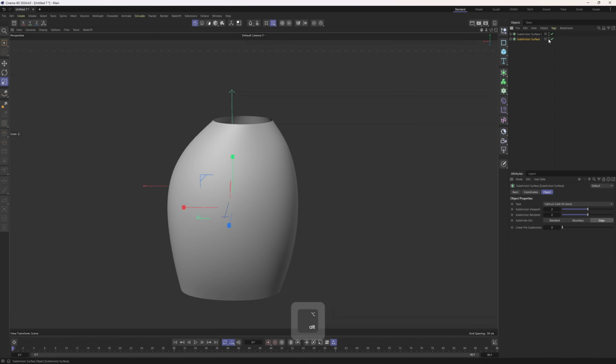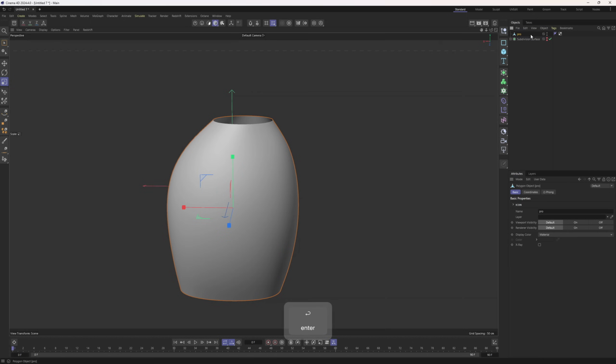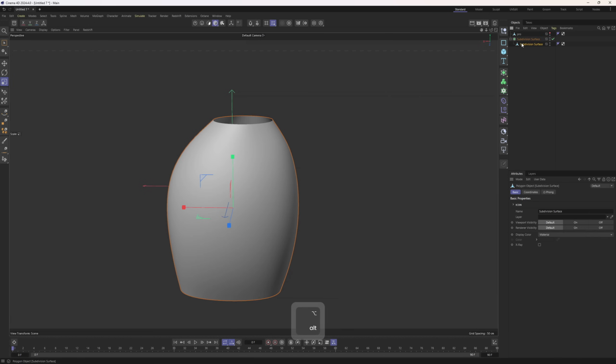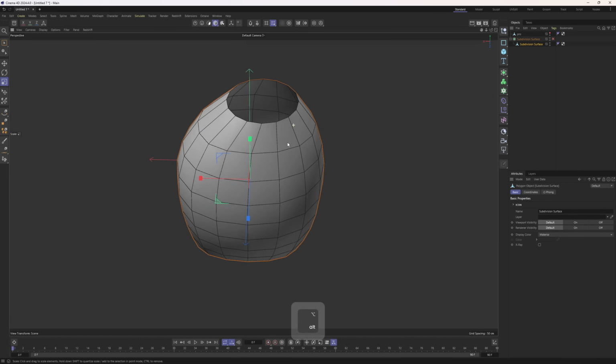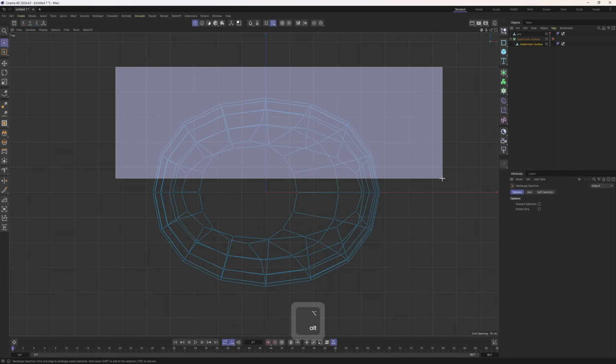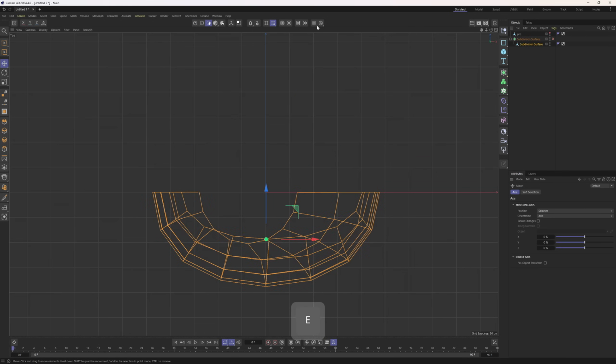Now let's duplicate this, hide it, and make this one editable. Hit C. I will call this projection. I'm going to hide it and unhide the low poly mesh. First things first, we could delete this half because I could easily mirror it on the other side.